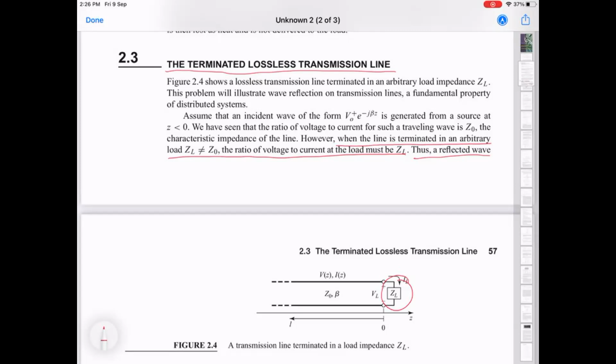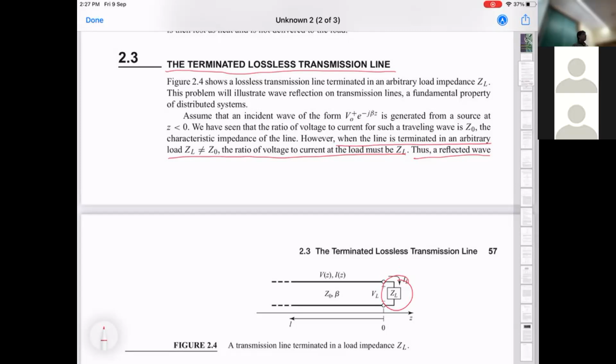What's different here is that connecting things like wires is not a benign operation at microwave frequencies, basically because the dimensions of those objects are comparable to the wavelength, or even larger than the wavelength, of the frequency of light we are talking about. And again, I will use light and microwave interchangeably because everything is electromagnetic waves.